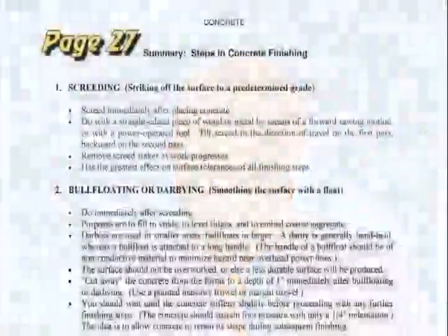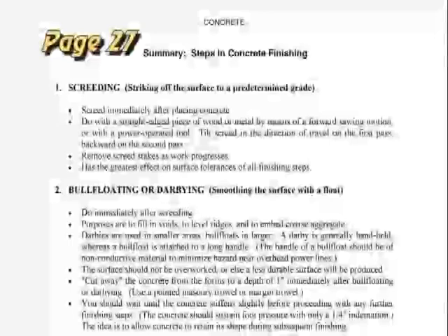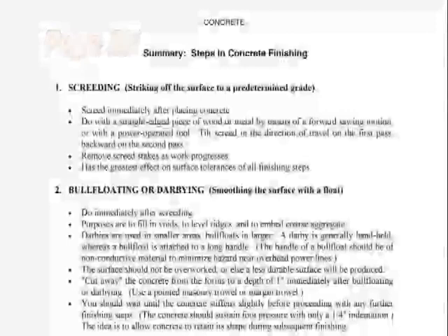Now that we mixed the concrete, put it on the truck, and dropped it off at the site into the forms, there's going to be some 7 or 8 different steps to get the concrete to look the way we want it to look. And in these steps, we're generally talking about dealing with a slab of concrete. The very first step is screeding. So let's take out our highlighters and underline that number 1 there, screeding, striking off the surface to a predetermined